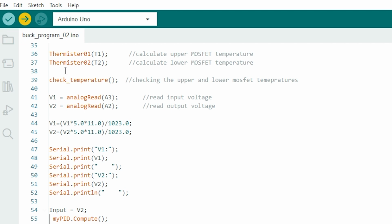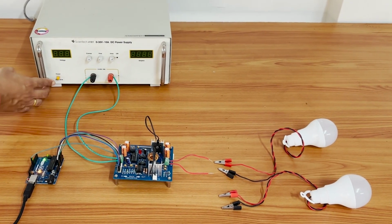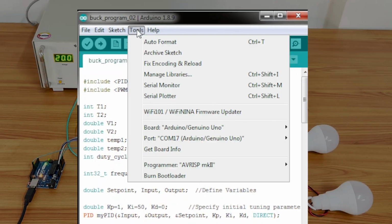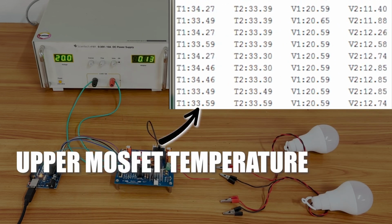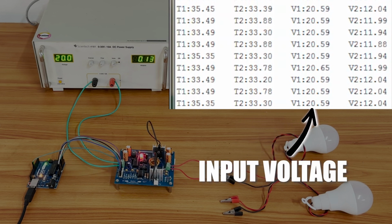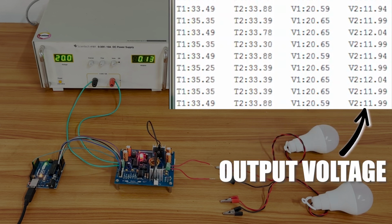Now we upload the program to Arduino board. We start the experiment by switching on the power supply. The input voltage is set at 20 volts. This time you can open the serial monitor from the Arduino tools menu. Here you can observe the upper MOSFET temperature T1, the lower MOSFET temperature T2, input voltage values V1, and finally output voltage values V2.